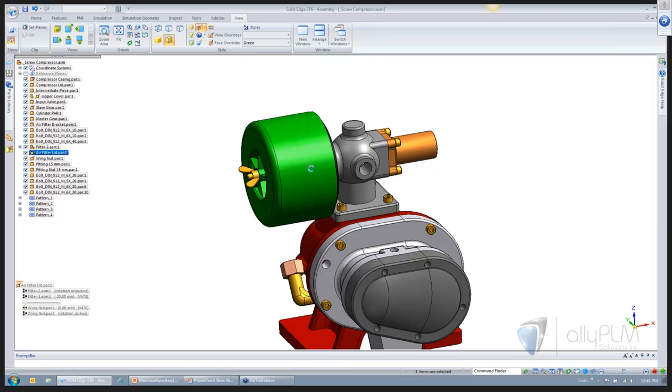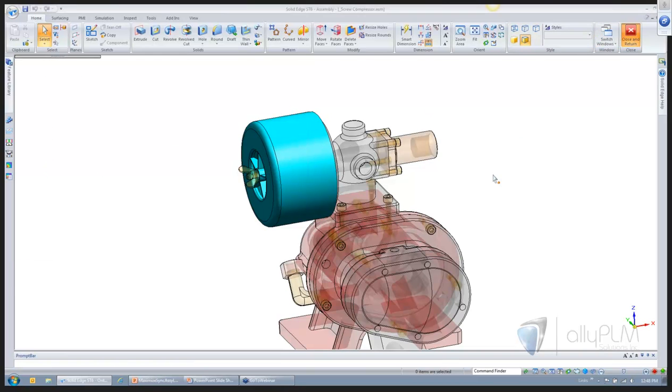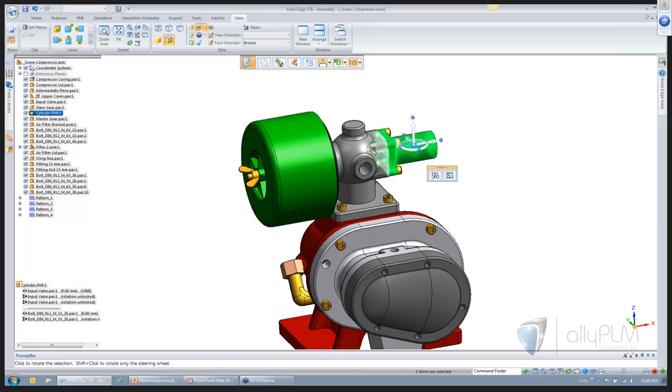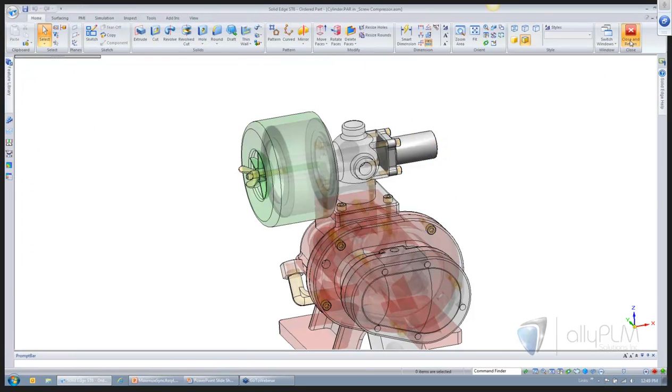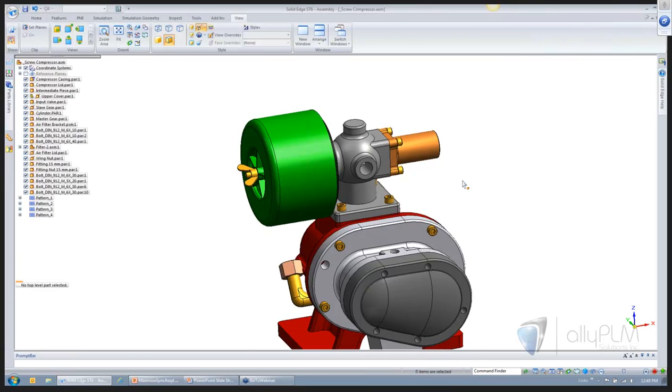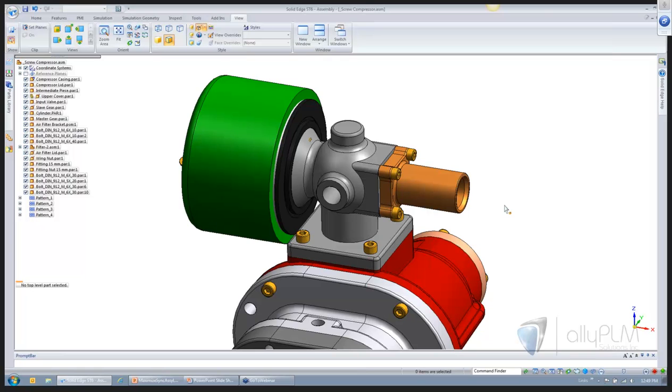I'm in a part priority mode right now, so when I select these parts and in place activate, I want to point out that this cover here is an ordered part, and the component here is also an ordered part. So in ST5, we had some new functionality that allowed us to edit the profile if we were using face priority. So I'm going to toggle to face priority, and you'll note that I'm not selecting faces on this part because it's an ordered part, but I'm selecting features.